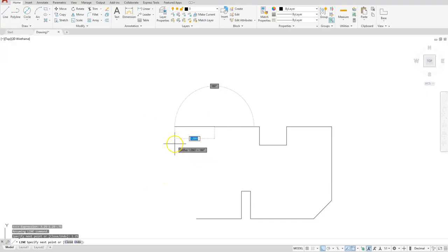Okay, so I'm at that point. Now, since you're going left in AutoCAD, that's going to be a negative number. So minus 0.75, comma, and I want to go down, which is also another negative number, 0.5. Once I select the Enter key, you will see that that line will go down at that angle. Okay, I'll go down a distance of 0.5.